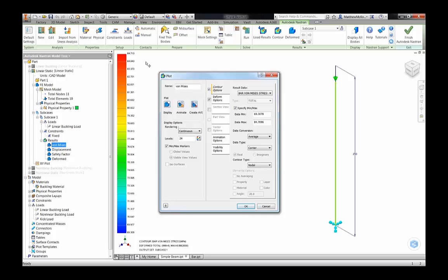In this case, our stress is around 85 megapascals, which is close to, if we assume the yield of the material, and like I said before, we may be using a material similar to alloy steel here, we're getting close to maybe half of the yield of the material. So which is really the criteria that we could look at. If we're getting around half the yield of the material, then we should be considering looking at a nonlinear study to validate the results that we're getting. In this case, we're getting around that range, about a third to a half of the value.